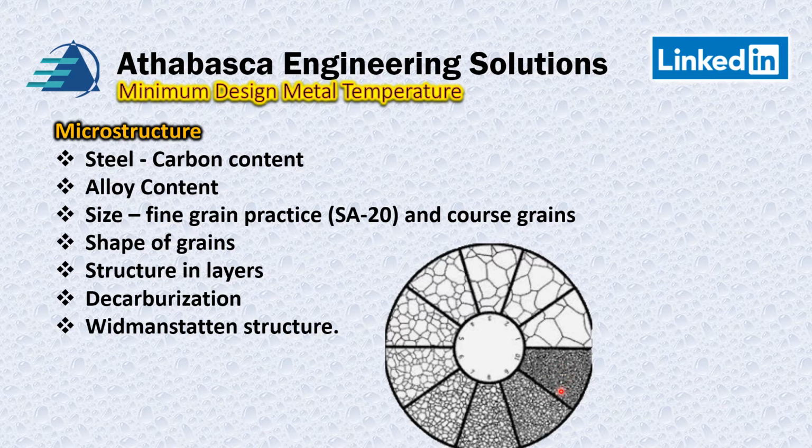The crack usually follows along the grain, so large grains have less distance for a crack to travel to finish, whereas fine grains have a great deal of distance. So in steel making, if you want impact tested properties, many specs will require that it's made to a fine grain practice.